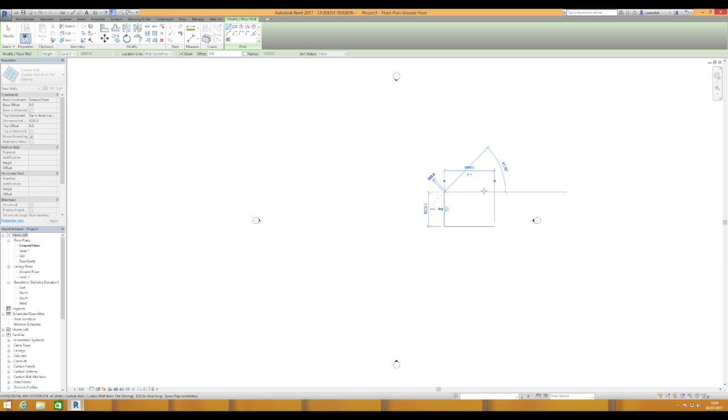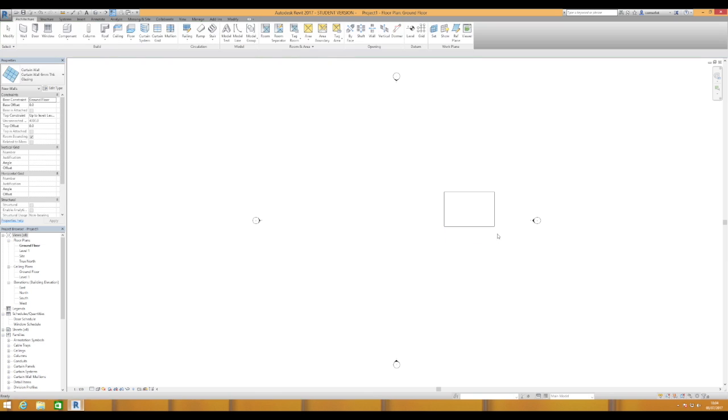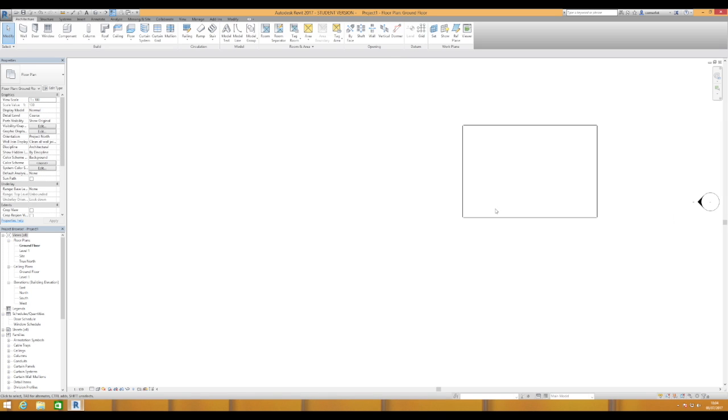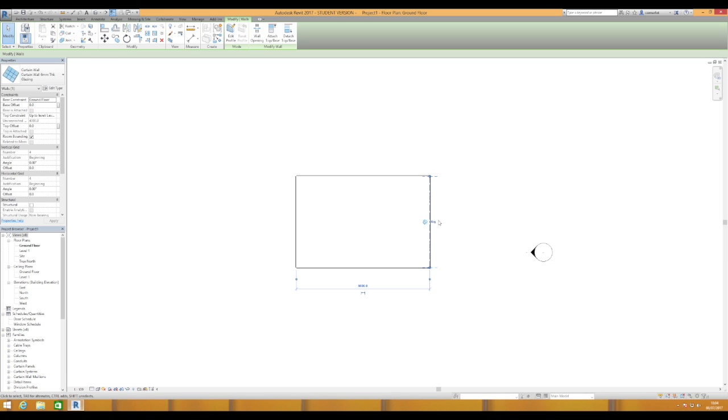If we're working clockwise, just like with walls in Revit, the walls are now facing towards the outside of that clockwise direction. Also, if we zoom in on those walls and select them, the flip arrows give you an idea whether you placed the walls in the right direction or not.